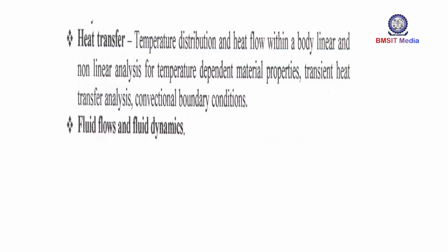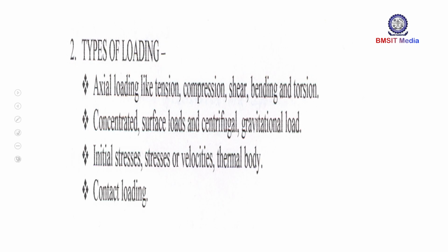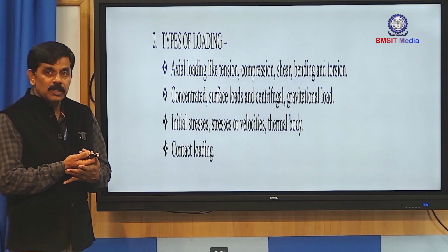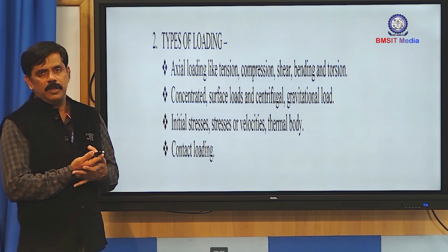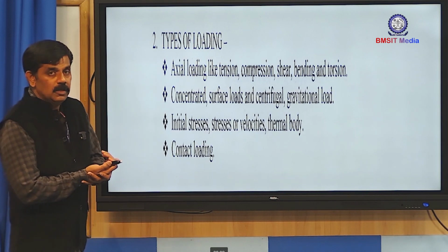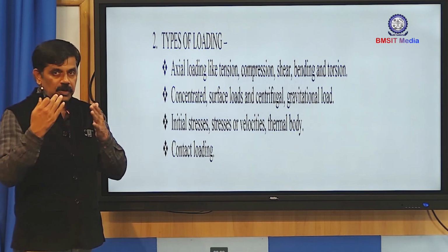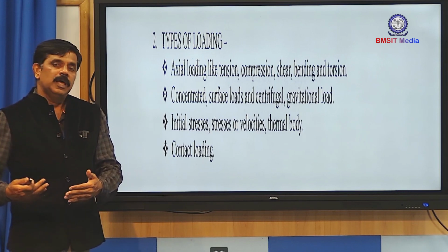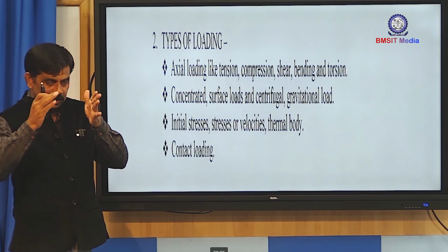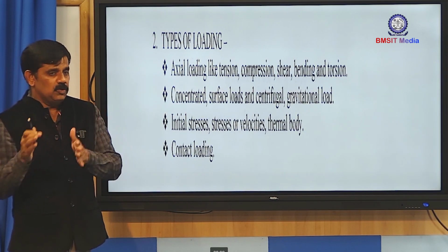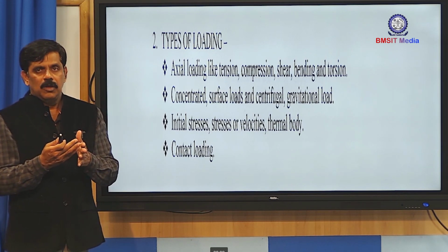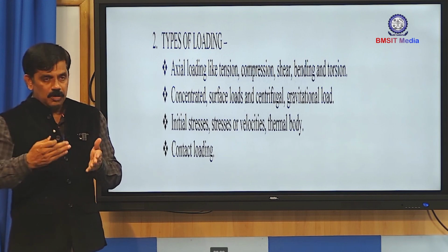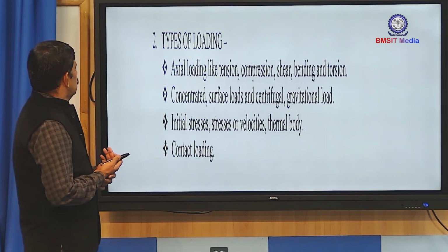and fluid dynamics. Then when you come to loading, once the member is subject to loading, there may be deformation. Because of the deformation, there is strain in the body. Because of the strain in the body, stresses are induced in the body. In the whole design, you are finding out the induced stress. Then you have to compare the induced stress with the design stress or allowable stress. Then you have to go for iteration, or change the material if it is not able to withstand the load, or change the cross section.